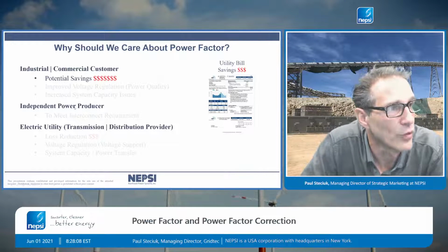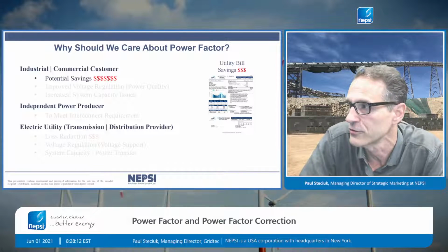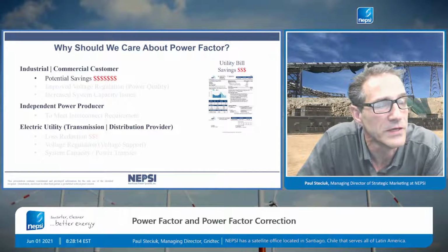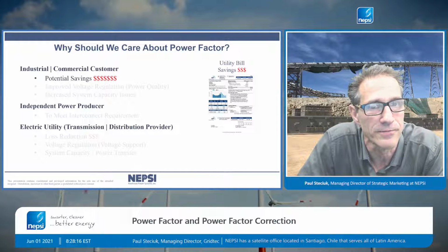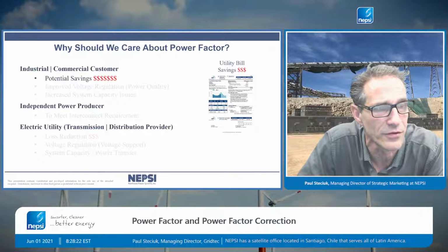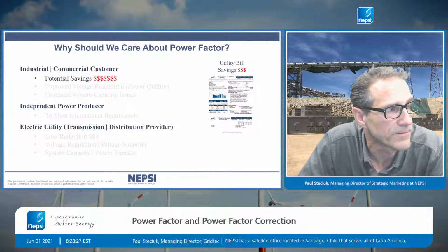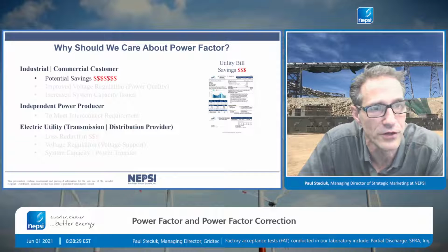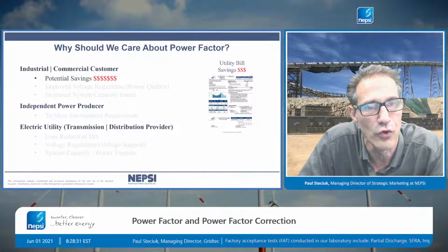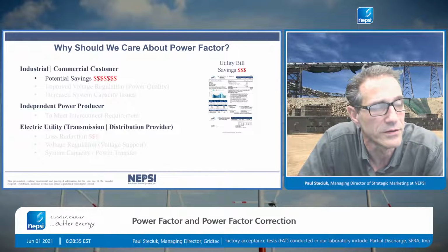But so why should we care about power factor, right? Why should we care about power factor? For North America, it's always associated with potential savings. Not always, but very often it is associated with potential savings. The industrial plants in North America will be charged for poor power factor. And we're going to get into reasons why in a few minutes.